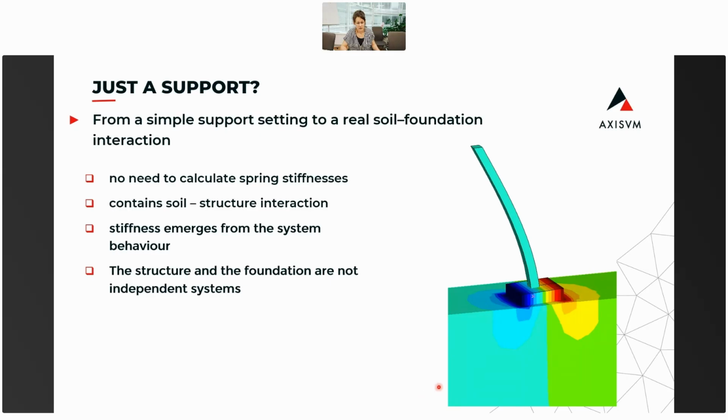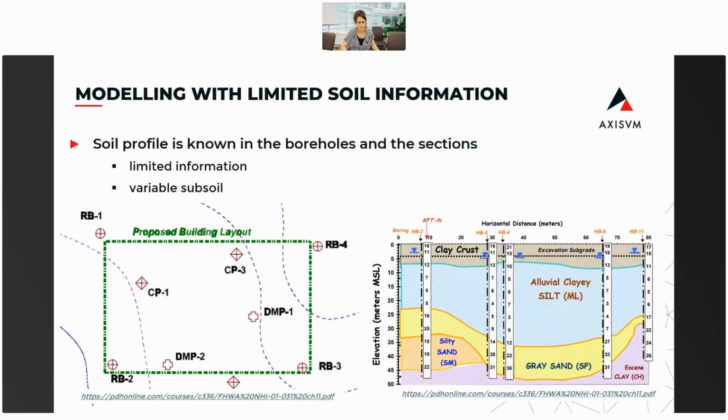This allows soil structure interaction to be considered in the analysis. Another interesting aspect is the available information about the subsoil. In practice, we often have limited information about it. We know the soil just in a few points under our building. So we know the borehole data, and we have to interpolate the soil layers between these boreholes.